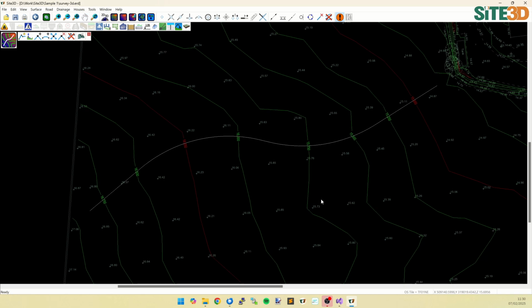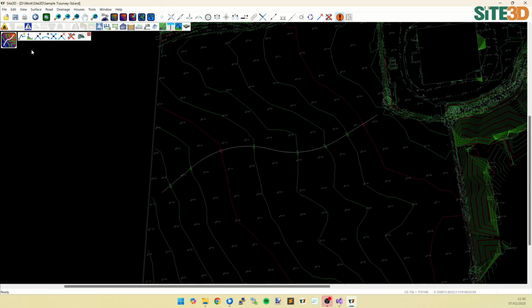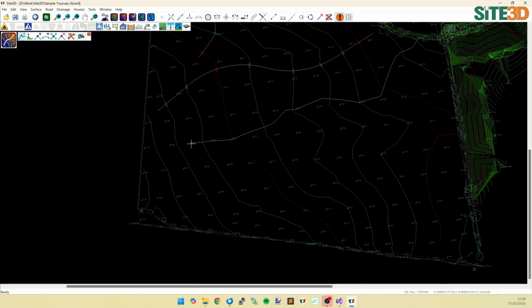We can add more than one on if you want to, but we also have the option to add in these cut lines using the water flow from point option. This will allow me to pick a single point on the surface, and it'll add in a contour cut line downstream from that particular location, so we can try out different positions. So we can quite simply and quickly go through our survey and add them in like this.